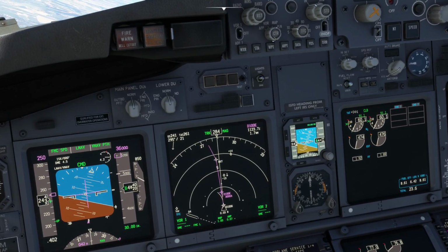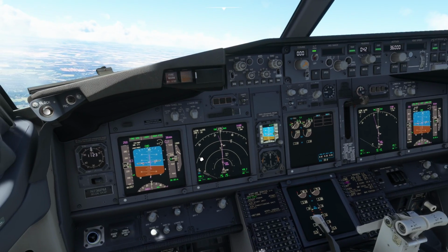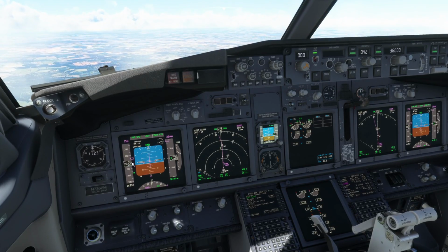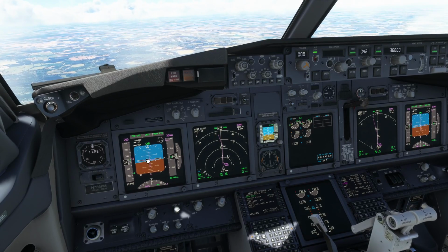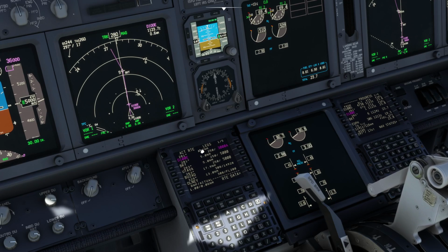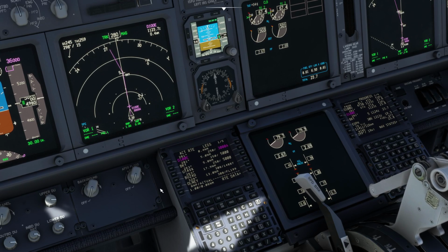Something that's worth pointing out as well, it should be straightening out. It's leveling out a bit late, isn't it? Okay, it's done it. So notice it's varying the throttle. It's trying to hit target airspeeds and altitudes as per the restrictions we saw earlier on the route. So 250 knots above 3,000, but no higher than 5,000 for the next one.